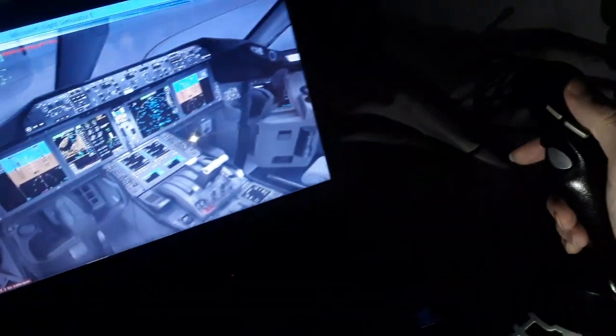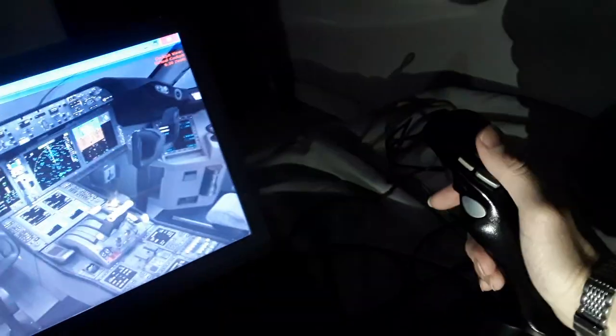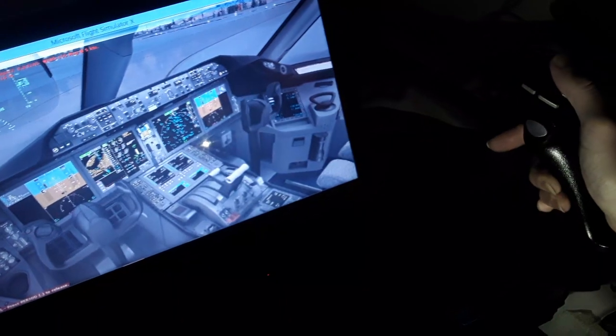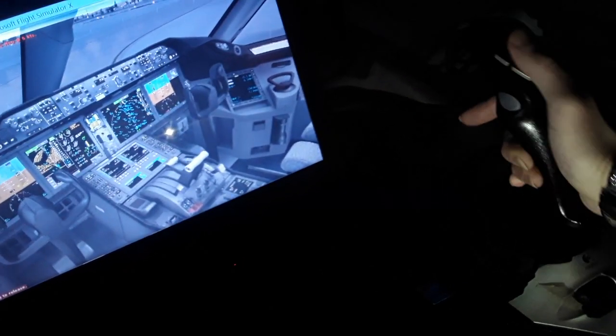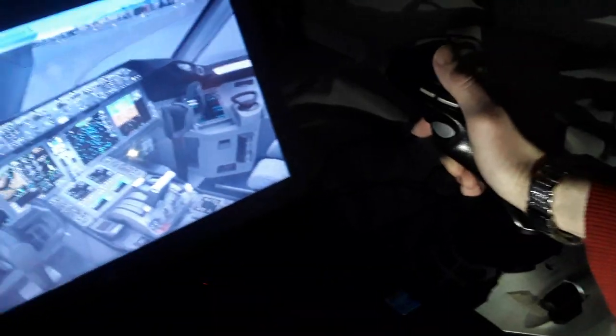So I'm going to show you now a little bit more of the flight controls over here. I'm going to show you also the displays. So you see both sides moving together, captain and first officer are interconnected. Also the side stick deflection is proportional to the yoke deflection, like this, as you can see. So it's quite fast, you can leave it neutral, and also the rudder pedals.